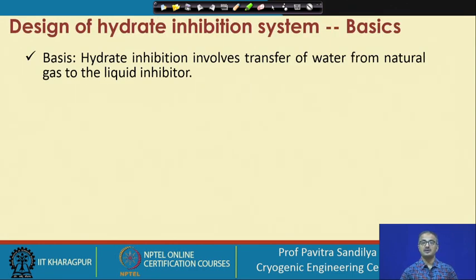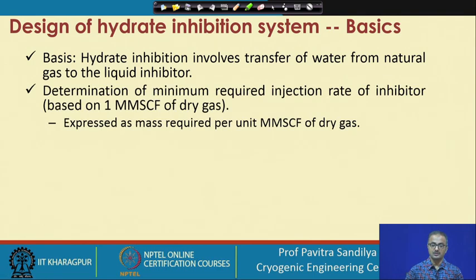Next we come to the design of the hydrate inhibition system. In this we shall be just looking at fundamentals without going into detail. The basis is that hydrate inhibition means that we are transferring the water from the natural gas to the liquid inhibitor. So what happens?